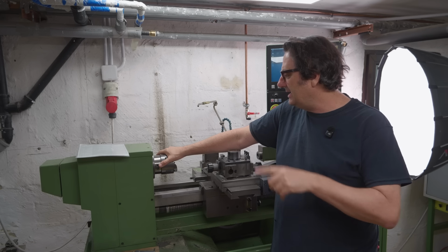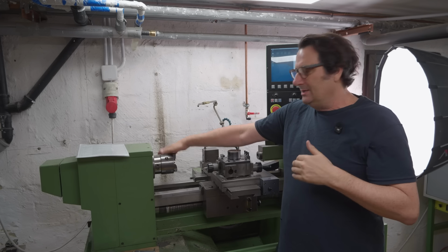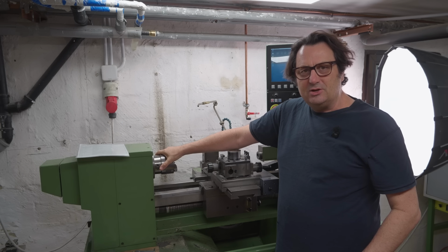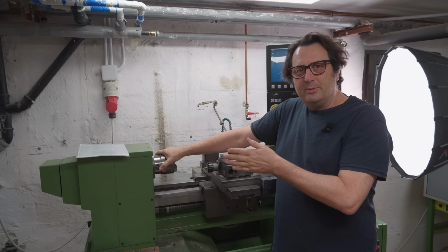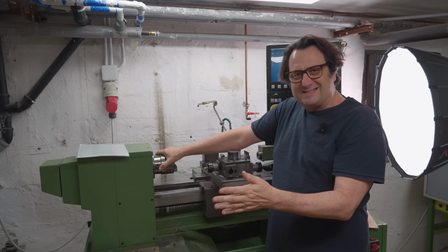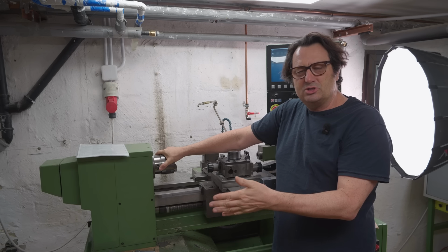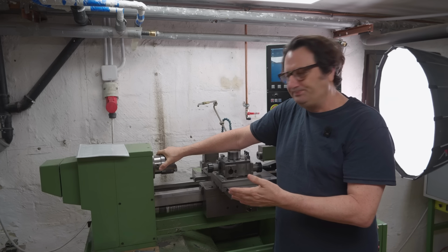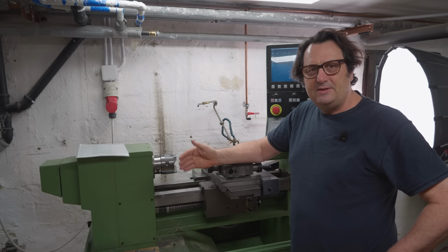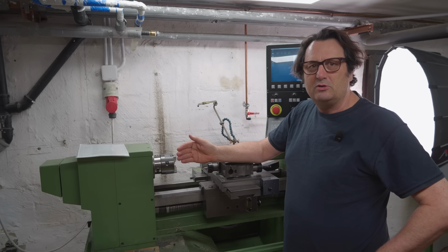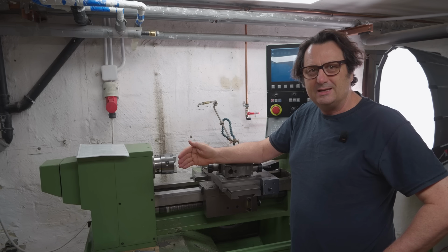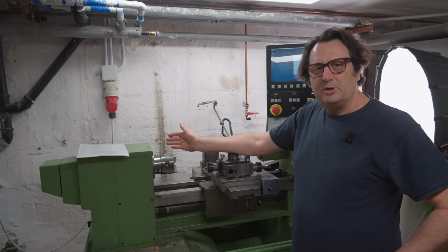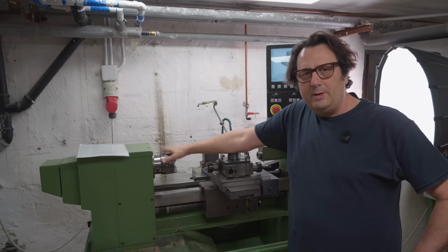The very first startup after starting the machine, the VFD starts to 10 Hertz, and then the variable transmission bumps right through for 6 seconds to end up on its slower speed stop. So we've got a known starting position. I've divided the CVT into 12 bumps of 0.42 of a second per bump, and then it's all just open loop. However, I did put a wee bit more in there.